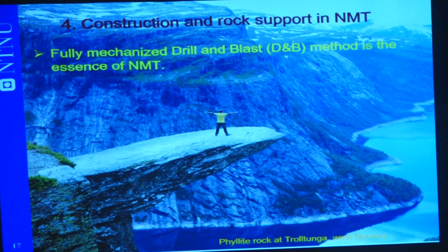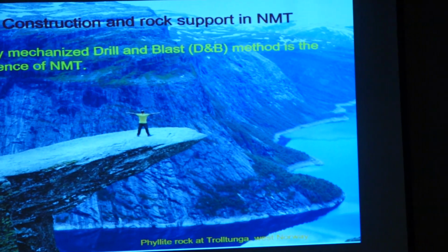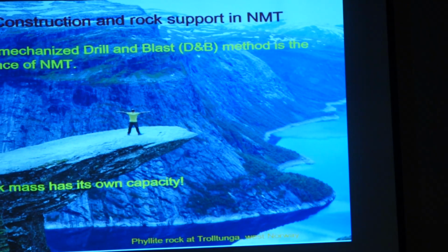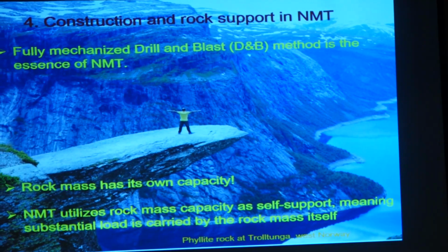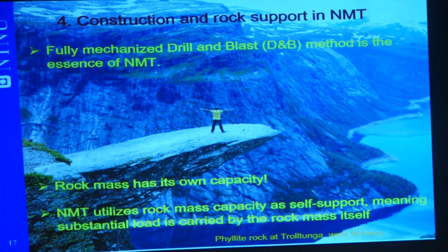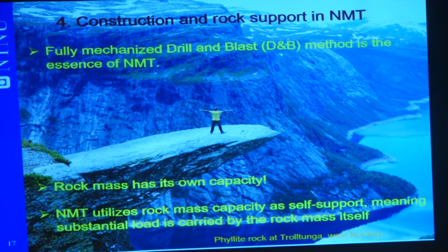So, the fully mechanized drill and blast method is the essence of NMT, of course. And the rock mass has its own capacity. I repeat again, NMT utilizes rock mass capacity as a self-supporting element. Meaning, a substantial load is carried by the rock mass itself.